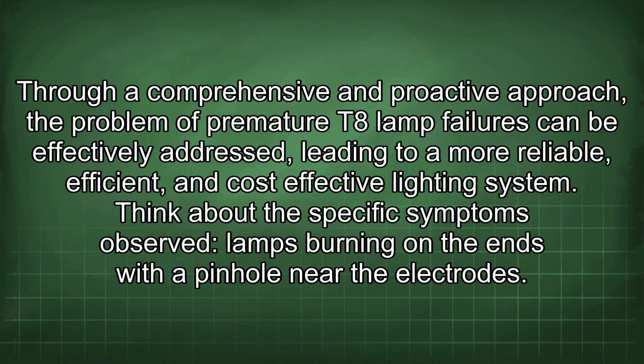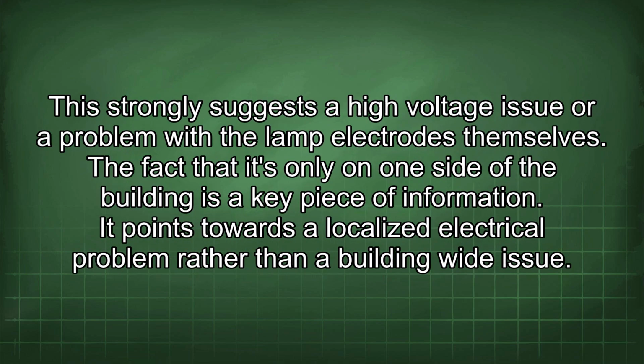Think about the specific symptoms observed: lamps burning on the ends with a pinhole near the electrodes. This strongly suggests a high voltage issue or a problem with the lamp electrodes themselves.